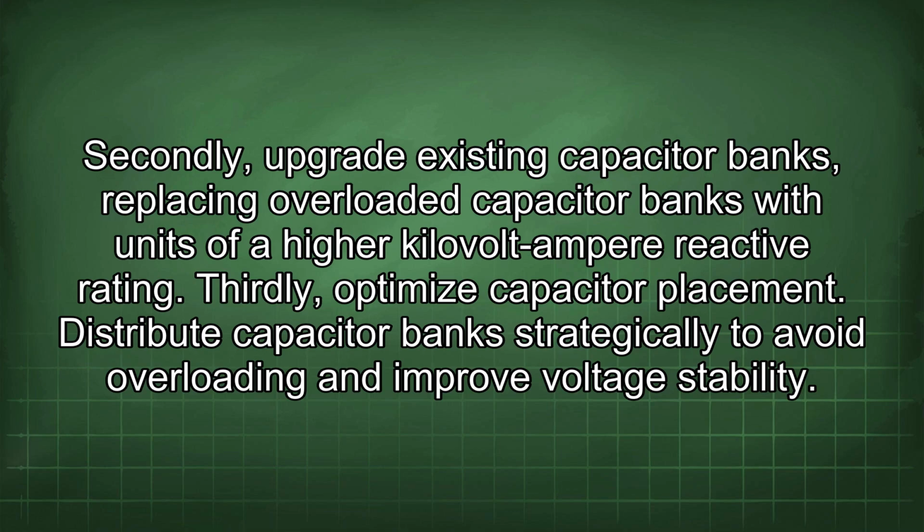Secondly, upgrade existing capacitor banks, replacing overloaded capacitor banks with units of a higher kilovolt-ampere reactive rating. Thirdly, optimize capacitor placement. Distribute capacitor banks strategically to avoid overloading and improve voltage stability.